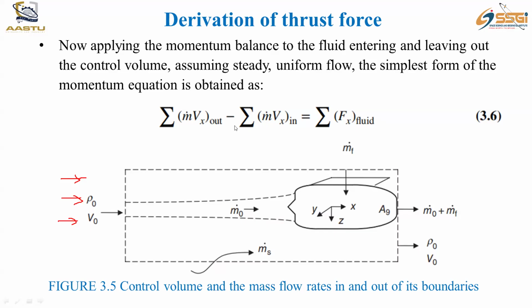So the stream of air is coming in this direction, which is characterized by the m dot node. This m dot is representing the area of inlet with rho V. So area times rho times V gives us the mass flow rate, in kilograms per second, of the air entering the system. From the side, you have m dot f.